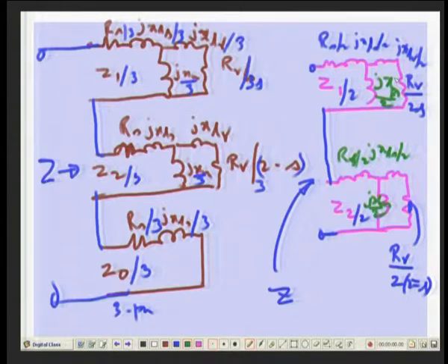I made a statement. In order that these must be identical, this Z must be same as this Z, right. You have no problem with stator resistance, because whether it is a 3-phase motor or 2-phase motor, the resistance of stator winding must be same. If this measures 2 ohms, that must also measure 2 ohms, right. Just because you do a different modeling, you can't make change. Leakage reactance stator is also same.